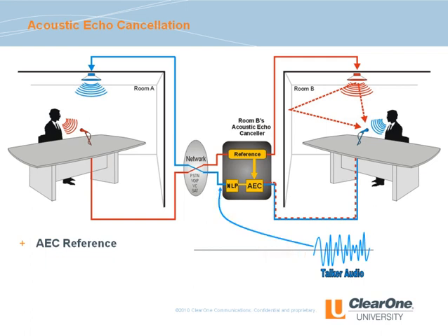However, in the real world, the AEC reference does not match the returned echo exactly. There are differences because the echo is altered slightly by the room as frequencies interact with the surfaces in the room and each other, resulting in residual echo. To resolve this, the AEC has an internal filter model that detects residual echo and uses it to adjust the AEC reference signal until it matches the acoustic echo coming from the room. This is an ongoing process called convergence.